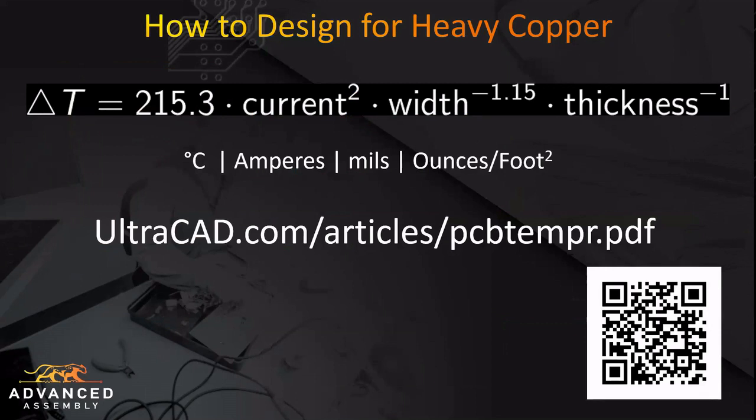If you're designing for a specific temperature change, that number becomes a constant. As your current increases, the trace width and/or thickness must also increase to compensate. Increased trace width does a slightly better job at dissipating heat than increased thickness. Back to Douglas Brooks's website, there is this UltraCAD URL that's posted at the bottom of this slide. There's more detail on that, and on the issues with the original 2221, and it discusses at length how to use the new equations and curves from the newly derived IPC 2152.